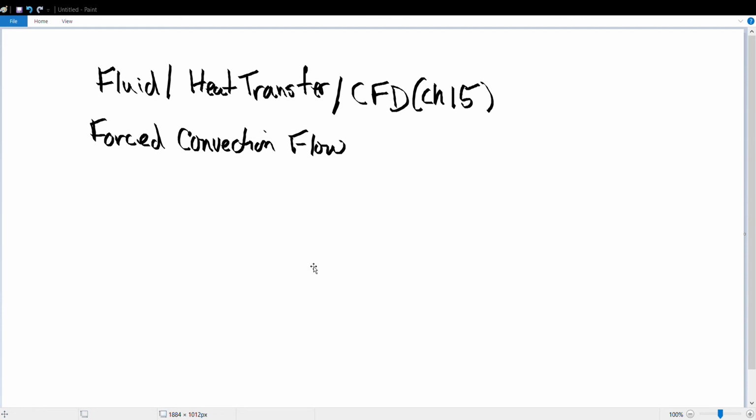There's a laminar part and a turbulent part, assuming that we are going from laminar flow and then we have a transition at X critical to turbulent. And so this is very typical of flow over a plate. The boundary layer, we didn't really get too involved with the profile, but in the last homework you were able to do some problems where you're estimating the boundary layer as a function of X, so X along the plate.